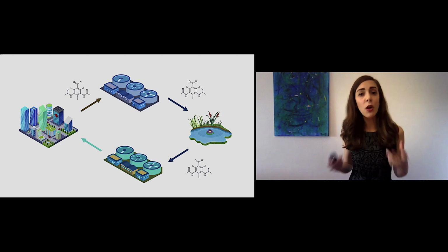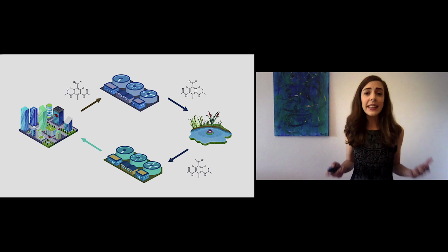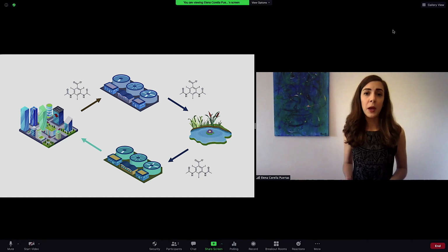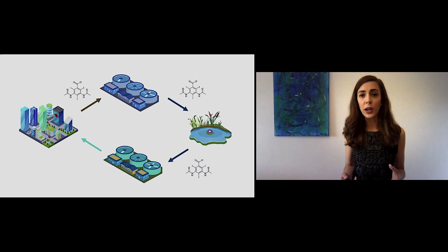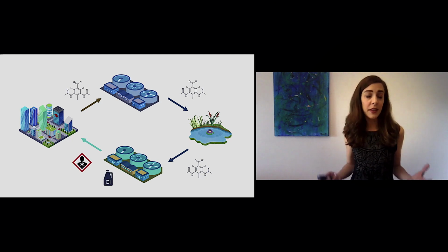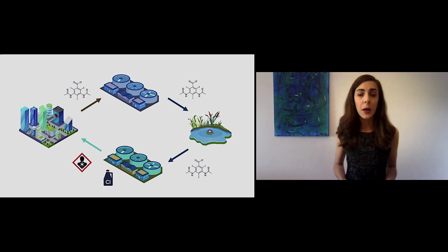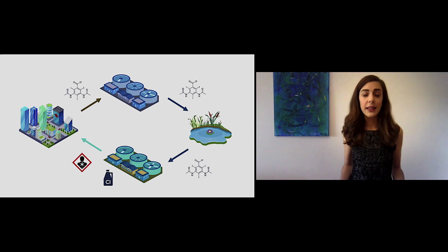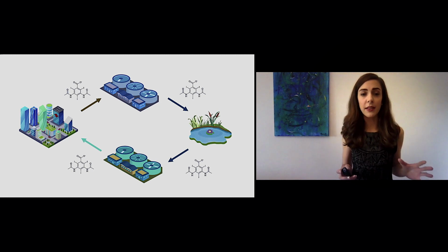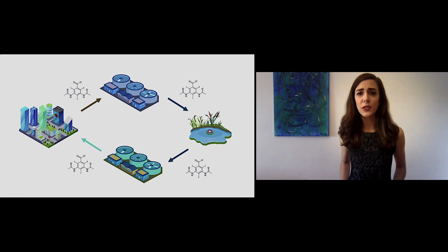and eventually it could also reach a drinking water treatment plant downstream, where at the latest there, we want the disinfection step because we do not want our drinking water to contain any bacteria or viruses. Again, in many countries around the world, this is done with chlorine, which just displaces the problem to later. Because chlorine can be quite problematic, some countries are thinking of banning it. And in that case, we have the problem that diatrizoate travels through the full water cycle and can reach us back through drinking water. So how do we solve this issue?